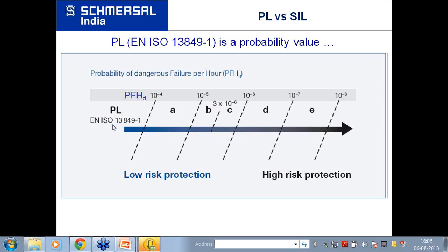Mr. P.K. Gupta has asked another question. Can you show the symbols used to mention the status pertaining to safety compliance so that it is easy to understand that the device is okay? Sir, one of the symbols which I had shown to you was the positive break contact symbol, the arrow in the circle. Now this symbol is only pertaining to the electromechanical safety devices.